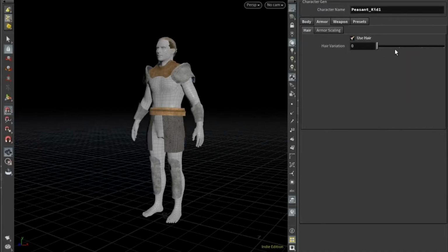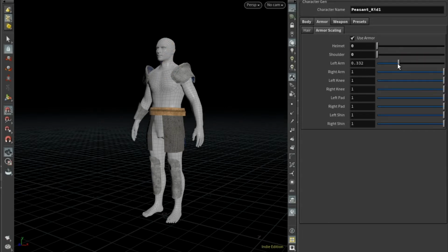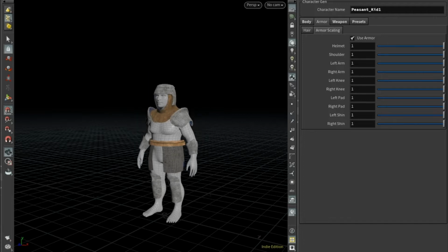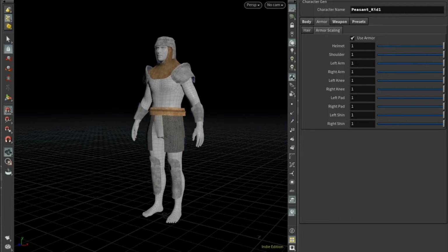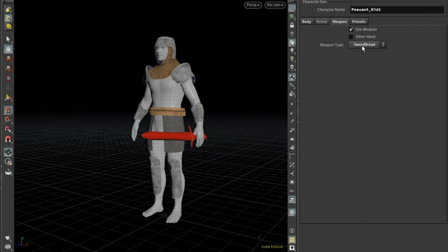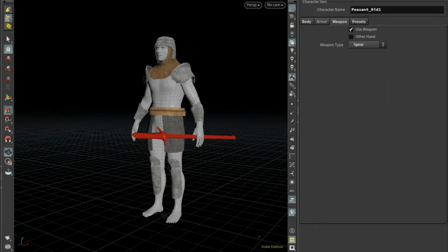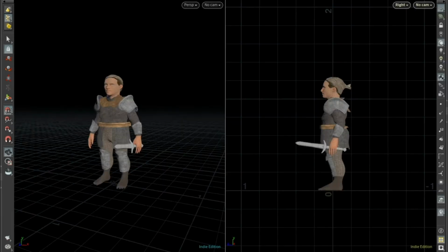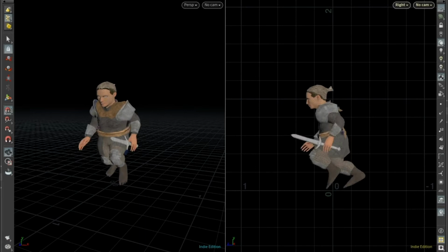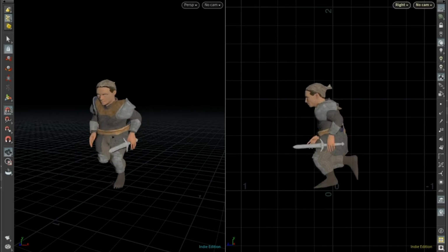Additionally, I added support for armor and weapons. The main controller allows changing each armor piece's scale and has additional control for morphing the helmet into different hairstyles. The armor also morphs together with the body changes. Same for the weapons, which morph into different setups. The consistent topology allows to work with one base mesh for all the characters. Finally, the armor and weapon receive the animation from the body with another point deformer.